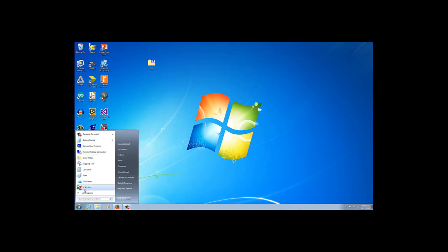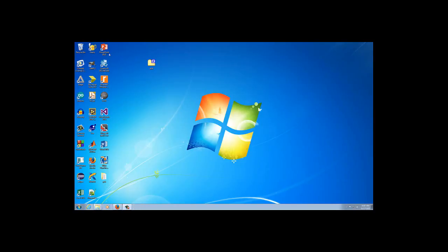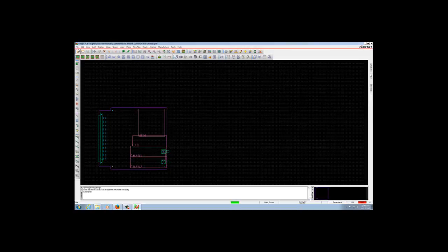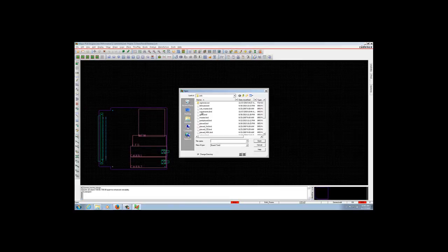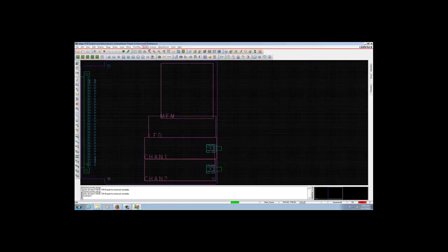Hi, we are going to do Lab 8 floor planning. Open the PCB editor and open the file constraints.board, and click on View, Zoom Fit so that you can see the entire board, and toggle the grid points on if they are not currently displayed.